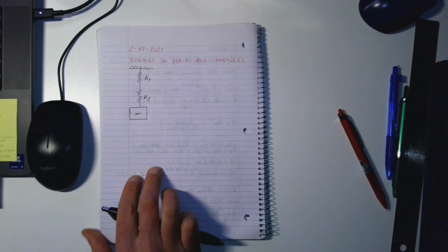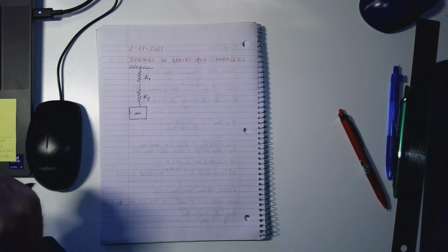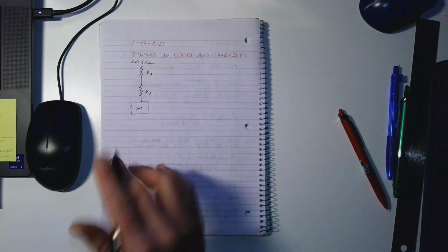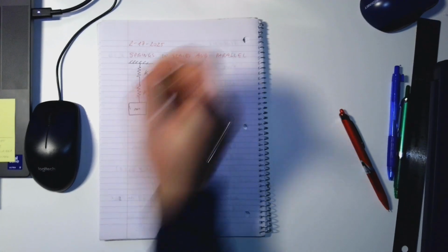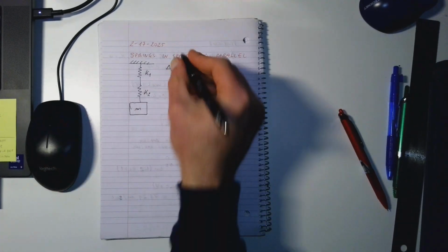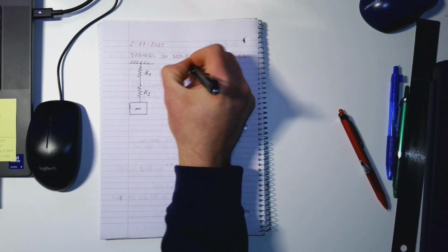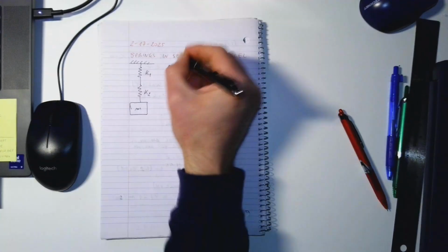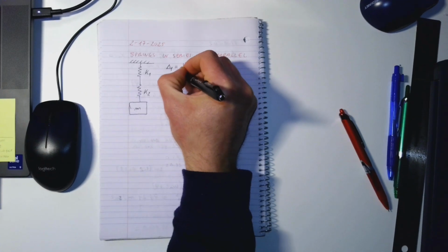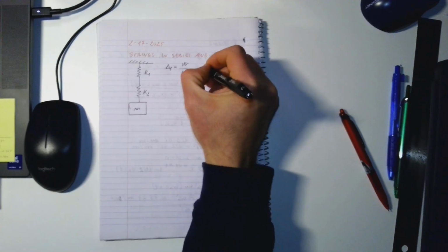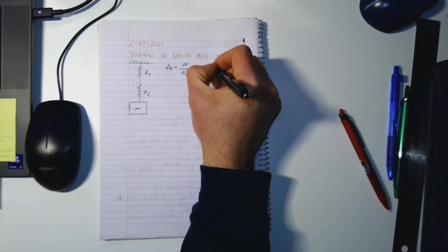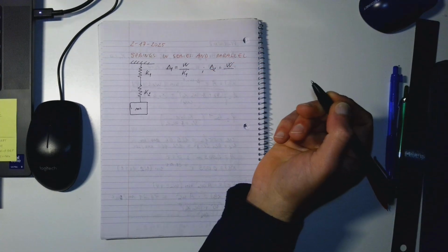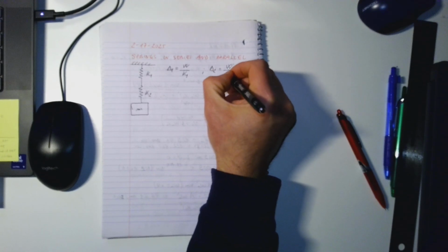So when we go back to the equation that define every single spring, we can write the following. We can write that delta 1, which is the displacement of the first spring, is equal to the weight, we indicate the force with W, which is the weight of the mass, divided by K1. Same thing for the other spring, we can write that delta 2 is also equal to W, again subject to the same force, divided by K2.